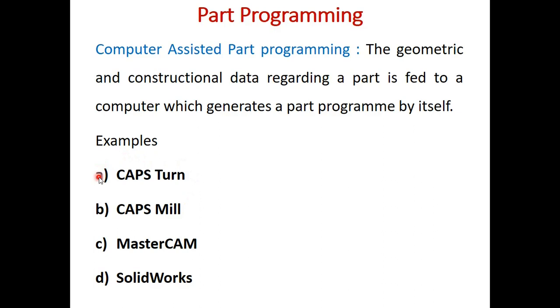software available for CNC programming, and these two, that is Mastercam and SolidWorks, have a feature of writing CNC programs. So in this one you can draw a 3D model, either of them, and then you can generate the CNC code by giving additional information to that.